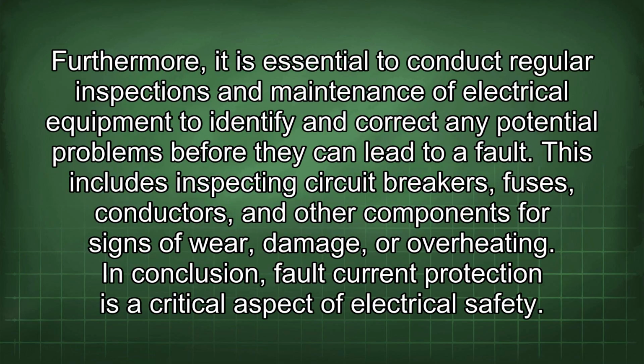Furthermore, it is essential to conduct regular inspections and maintenance of electrical equipment to identify and correct any potential problems before they can lead to a fault. This includes inspecting circuit breakers, fuses, conductors, and other components for signs of wear, damage, or overheating.